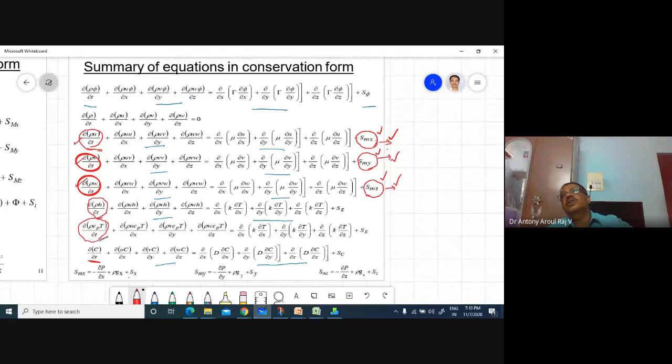That means throughout your flow domain, wherever such components are present, for example if you are modeling a strainer, filter, and other components, in those places you can just give the source term, a plus value or a minus value. Automatically, the flow will take care. So that is the advantage. For modeling complicated components in the flow domain, these momentum terms will come to your help.